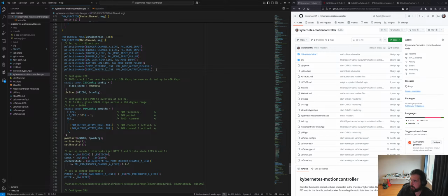Whereas something like STM32, which is what ChibiOS mainly would work with, all ARM CPUs have, okay, I really don't want to make that claim, but I'm fairly certain that all ARM cores, especially in the microcontroller space, have a unit called the SysTick unit, system tick unit, which is a timer specifically for doing timing tasks in your logic, so that all of the more advanced timers are free for doing hardware.